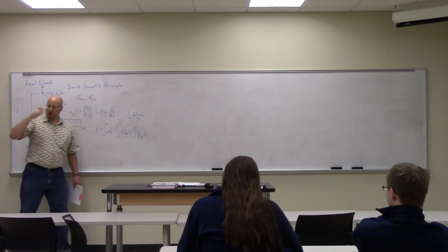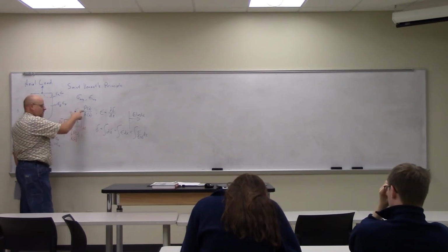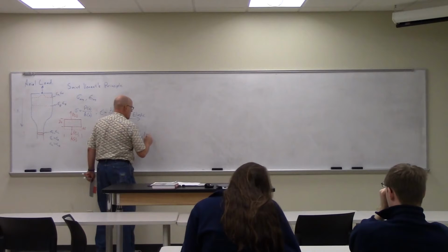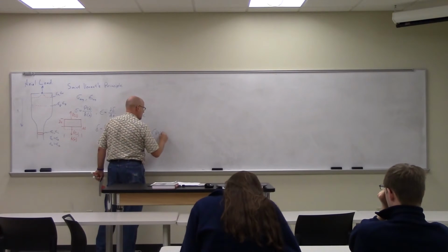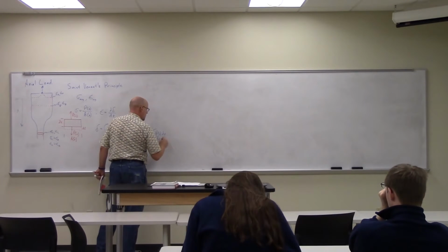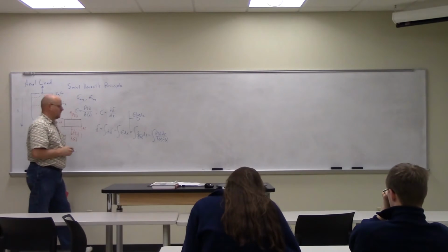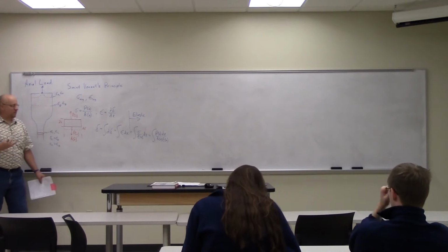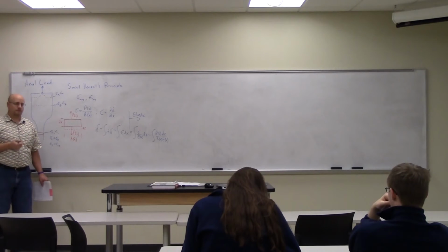Right, so we're in that linear proportional region. But sigma is P(x) over A(x), so it's really the integral of P(x) dx over A(x) E(x). That's my total displacement.